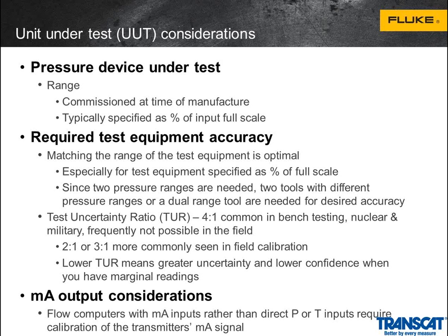So if you ran that same calibration again, there's a reasonably good chance that you might find that the unit is in calibration. And now you have a problem because you have an in-tolerance reading and an out-of-tolerance reading. Which one is correct? And so then it becomes very, very difficult to figure out, well, what do I do next? You know, is this reading valid or should I make an adjustment?